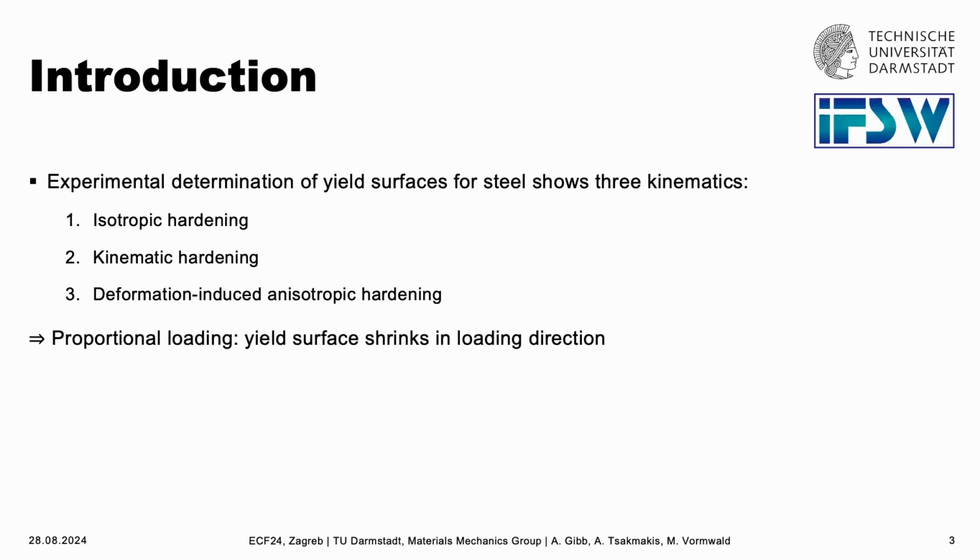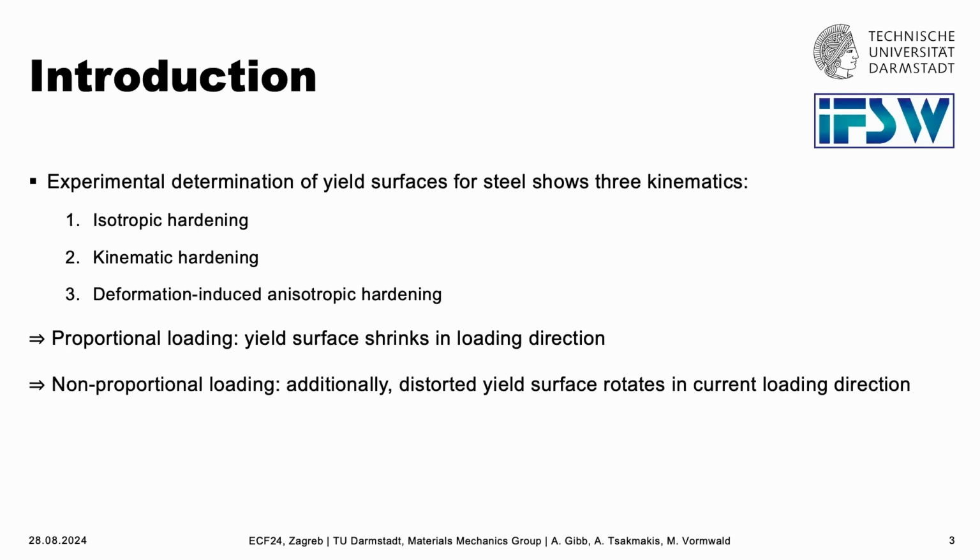What it actually is, if we have proportional loading cases, we will observe that during this loading, the yield surface will start to shrink in the loading direction. And for non-proportional cases, additionally to the shrinking, we can see that the yield surface will start to rotate.